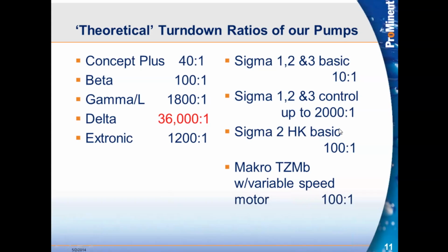We know that there are applications that run below that 30% recommendation, for sure. 30% is what they're saying will activate those valve balls properly on the stroke length. So you need a certain volume per stroke to efficiently be able to actuate the suction and discharge valve balls.